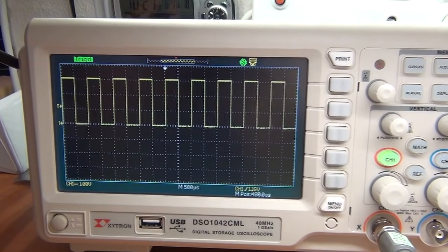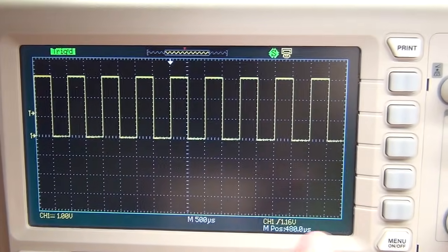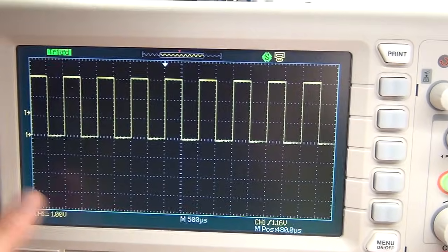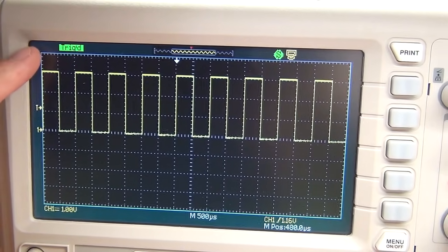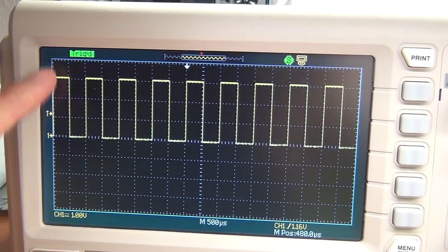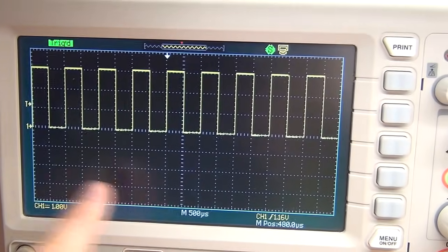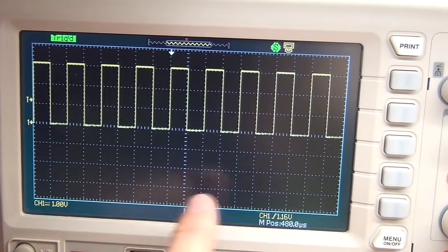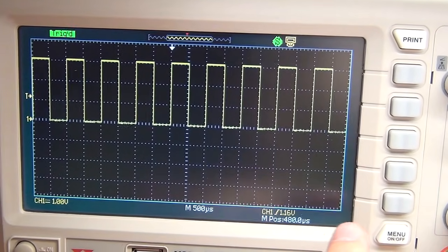So what I want to represent here is what we've just chatted about, is that whole matrix that you have on your display. My oscilloscope isn't a 10 by 10. As I recall, there's 8 divisions going up representing the signal level or the voltage, and then mine has far more across the time axis, which I really like, because it allows me, if I've got a slow signal, more time to actually view the signal.